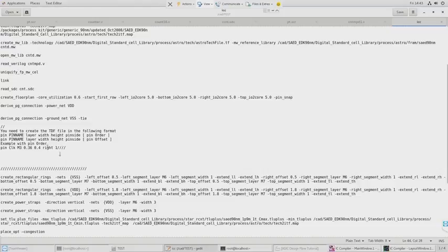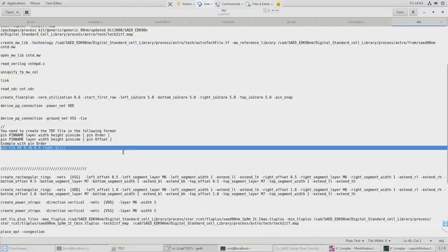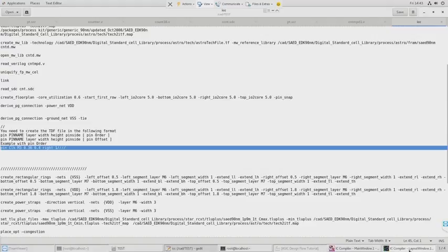Okay, so based on this, you can specify your corresponding input output file, and you can just import that to IC Compiler, so that according to you your corresponding IO pads will be placed. So here actually I am choosing the default option.